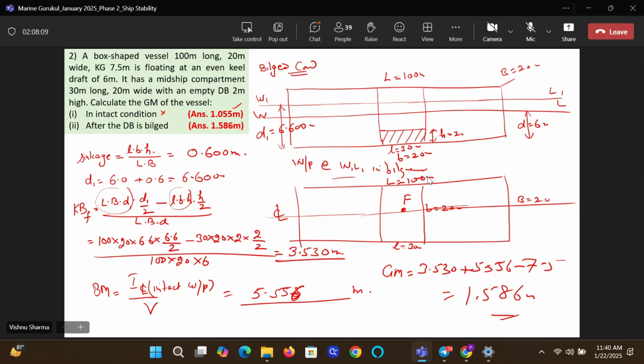So, guys, will you be able to calculate KB if required by moments, by talking to yourself, making those statements? Vertical moment of underwater volume up to W1L1 minus the vertical moment of the volume under the water not contributing to buoyancy, divided by volume of buoyancy, which is LBD. So you should be able to calculate talking to yourself.